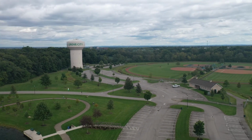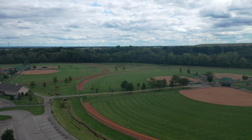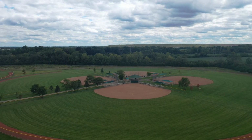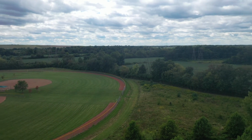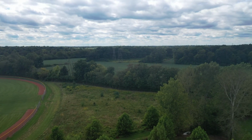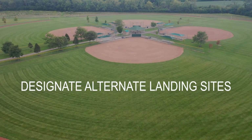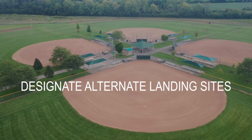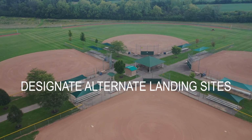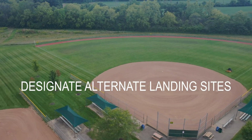If there are, it's a good idea to take photos from different angles of the different problem areas so you can take your time and come up with an adequate plan to ensure safety. While you're there, you'll also have to take a look around and survey for possible alternate landing sites should the primary landing site become compromised.